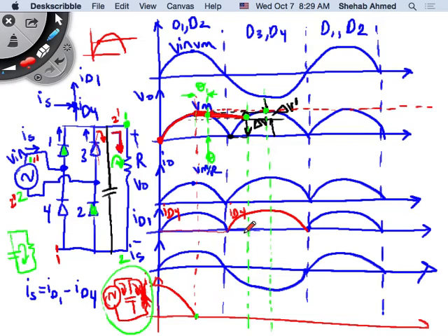So what will it look like? As soon as the capacitor voltage is less than the supply voltage, the supply will try to charge the capacitor. As soon as I connect the supply across the capacitor, it will try to push the capacitor voltage to be equal to the supply voltage. And current through a capacitor can change abruptly. The current IC equals C dVc by dt.